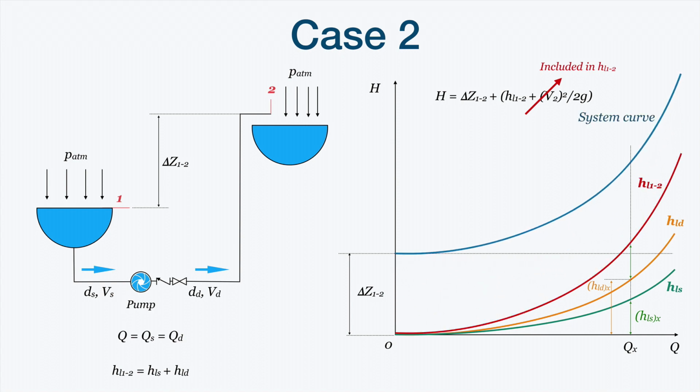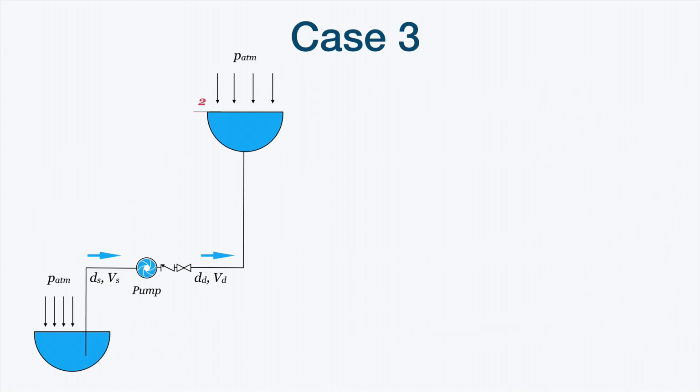So to find the system curve, we have to move this curve over the static head line to obtain the curve of the whole system with the corresponding value of the head Hx. We will do the same for all these cases we are analyzing today.